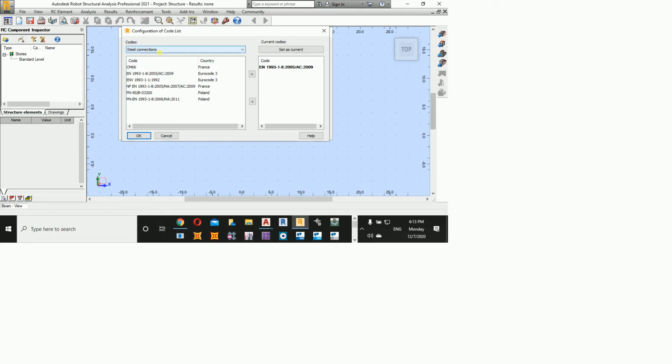After steel connection, can we go for RC? Now, if you see here, we have different codes which are available. Okay, we have ACI and we have BS. Can you see on the right side? Do you have ACI and BS? By default, it's ACI. ACI 11 is a 2011 version. ACI 11 metric, that's for metric units. 14M, that is the newer version. And then we have BS 8110. If it's not available from here, you can choose it and then shift it to the other side.